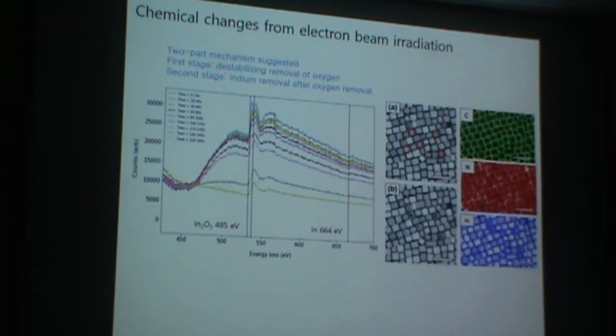What we can also see in the elemental mapping is the substrate. We can actually see the indium oxide nanocrystals being drilled completely through, all the way through the silicon nitride grid, which we've been using to support the substrate in the STEM EELS. So we can indeed confirm that the holes are completely disintegrated all the way through.